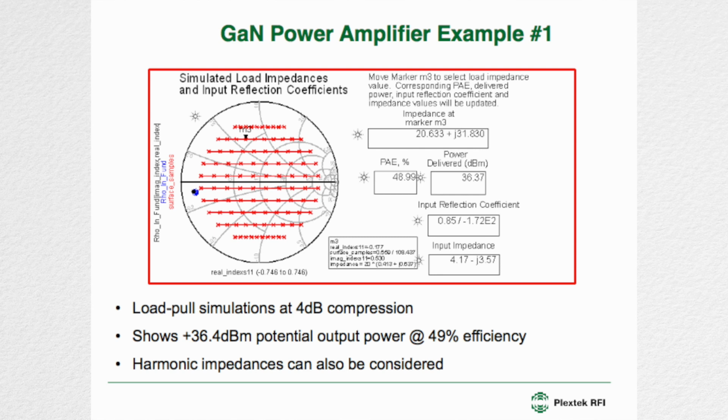What the simulator does, we present all these different load impedances here, and we measure the power and the PAE and the gain, or rather the simulator does. And from this, we can plot the load contours that Steve spoke about earlier. And I'll show some of these later for some of the other examples.